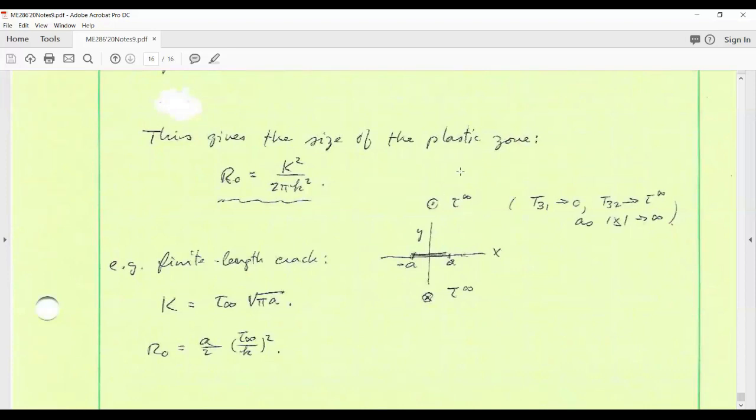By large, I mean, let's suppose that the external boundaries of the material are so far away from the crack itself that you can regard the external boundaries as being off at infinity. Position goes to infinity and radius goes to infinity. And suppose that remote from the crack, so there's a boundary here on top far away, and we're loading it, we're prescribing an anti-plane shear traction coming out of the screen at you. So that's the tip of an arrow here coming out of the page.